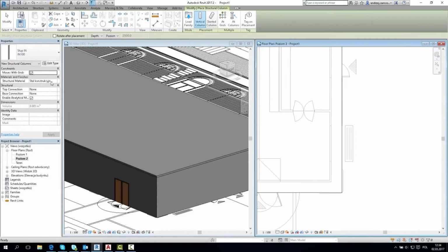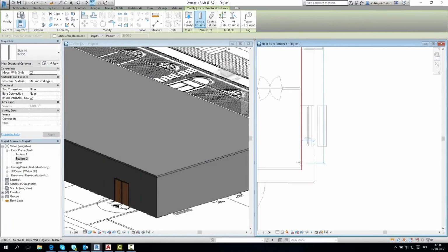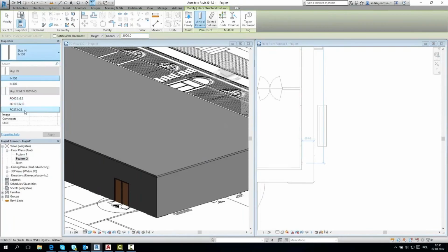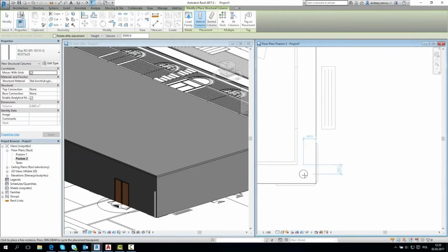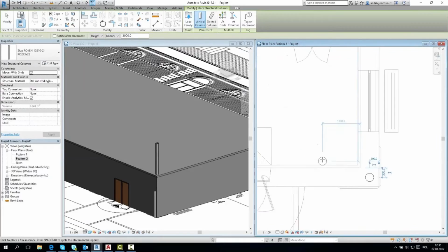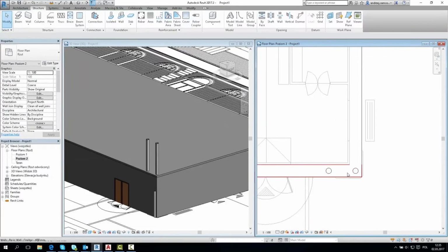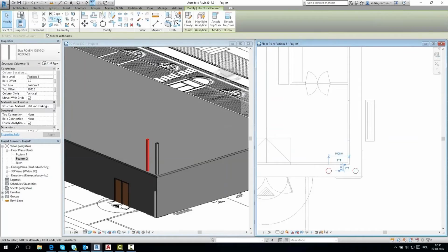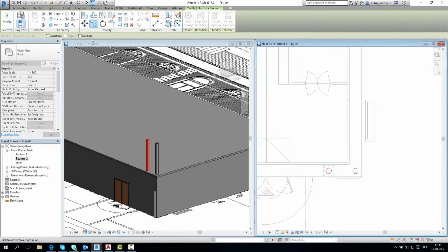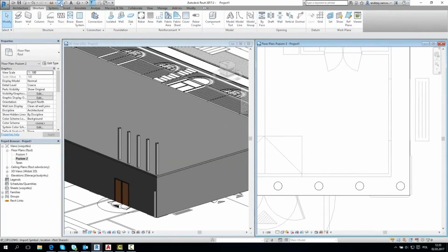And for example, like in AutoCAD you can make some arrays, here let's have a look, I want to create some columns. So you can see I will create a column, so I can pick a column where I want to put it. I have to be obviously in the proper elevation, and now I can say, okay, this one and this one are columns 1 and 2. And like in AutoCAD you can create an array. Here what I can tell the system is, okay, now I have this distance and I want to repeat it, creating the same array of the columns.